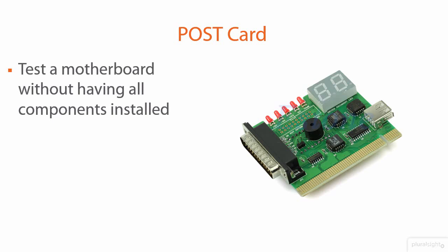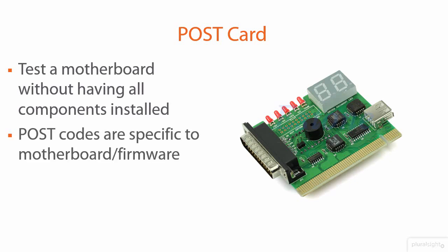With a postcard, and it's kind of funny, postcard, yeah, it's not something you send through the mail. Notice that they have several inputs. There's USB, PCIe, sometimes parallel, so I've used them with plugging in the postcard directly into a PCI Express or an old school PCI slot, and you can test the motherboard without having all the other components installed. So you power on the system and you can at least get a post code, a non-error state post code. That is, you won't get like keyboard unplugged error or something that's expected. If you get a post error, it will be something genuinely useful.